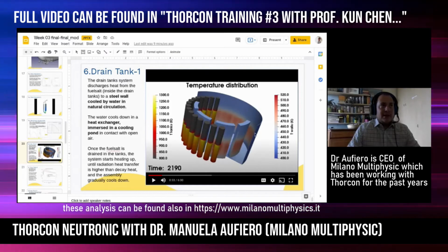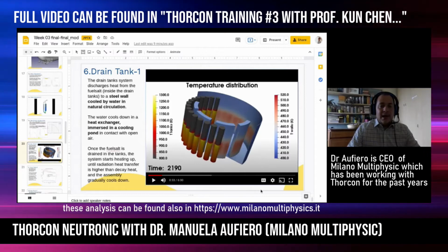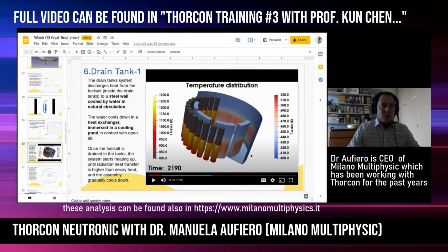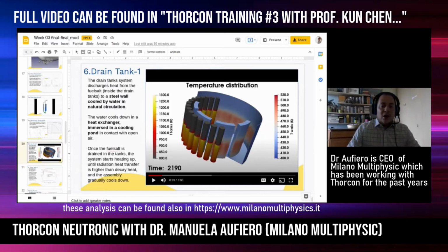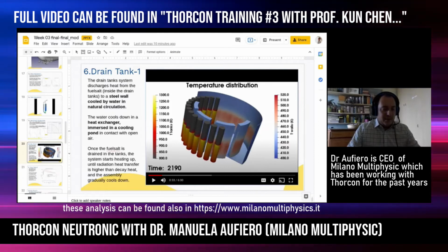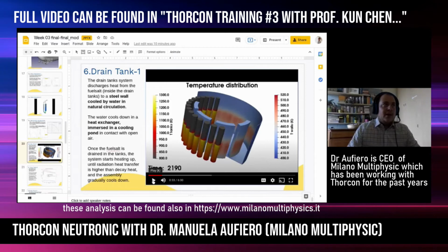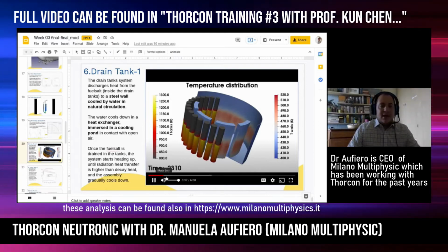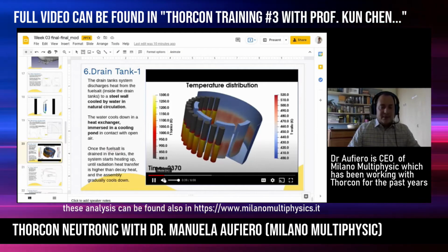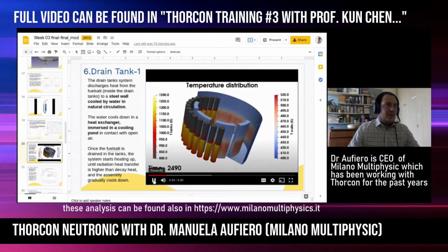It is expected that water reaches a boiling temperature and nucleate boiling increases the rate of heat removal. Not depicted here is the circuit of the water going and steam going towards the pond and releasing heat in the pond, which provides a long-time heat capacity, and finally to the air in the following time.